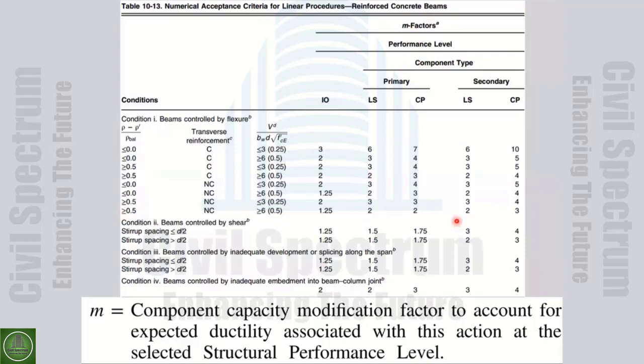deformation control. For force control, we don't have anything to do. Force control shouldn't pass the strength. Easy. And the strength is calculated with the lower bound value of the material characteristic. And that's it. Everything, all the discussion, all the new things, all the exciting things are about the deformation control, about the fuses, about the locations that can get damaged.